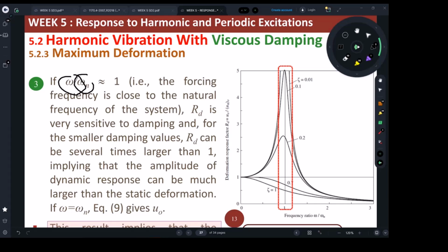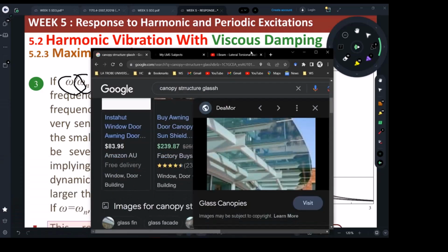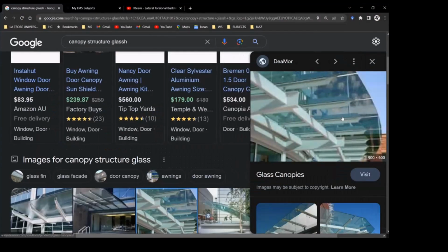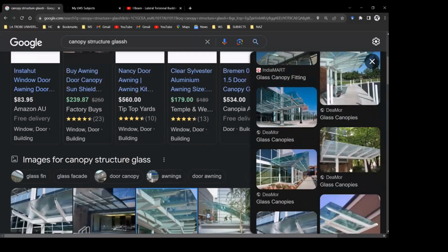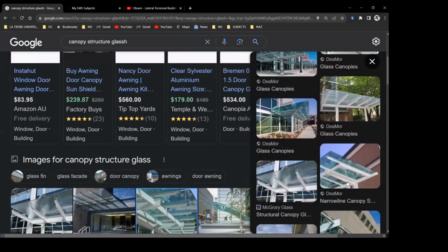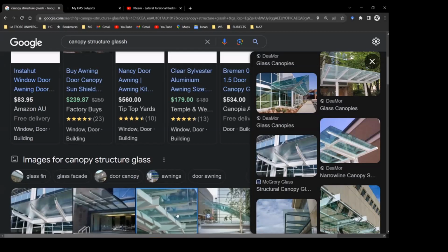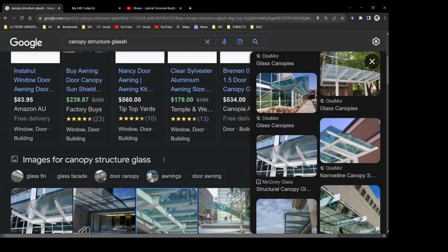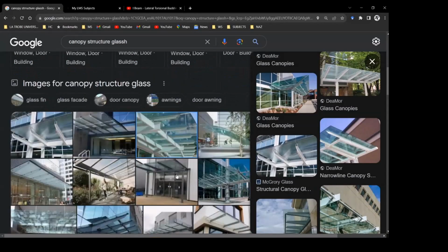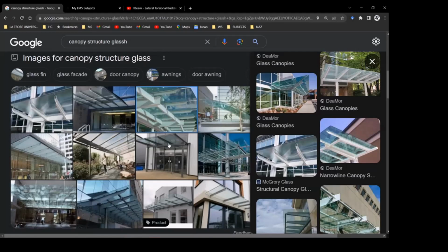Yeah, like these kind, but here we go. You know these things? These usually need careful dynamic analysis, like these kind of things. You see them, they are all the way around in the city, and they're very sensitive to vibrations. And the building won't feel any vibrations, but these will. And that's where you can introduce some dampers, just some rubber, to actually absorb all the vibrations.